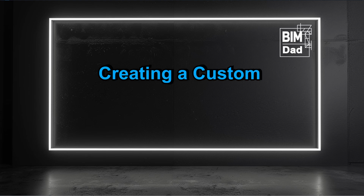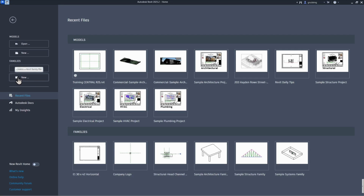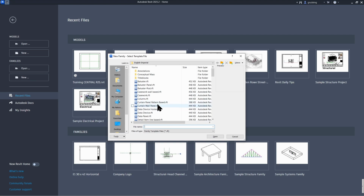In this video, we'll be looking at creating a structural column family. Some of the concepts that we'll be talking about today do apply to general families. So I'm going to go and create a new family. I'm going to choose a structural column family and hit open.